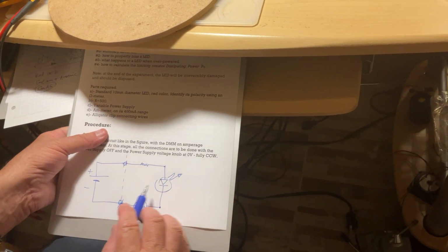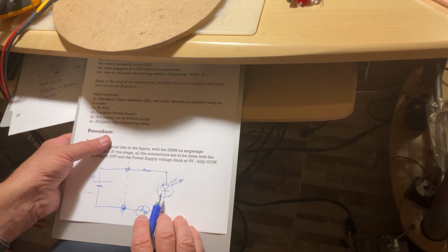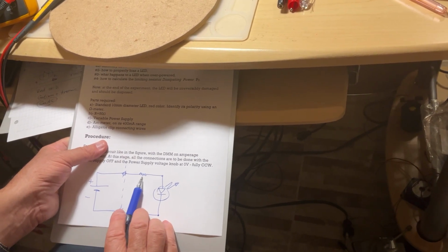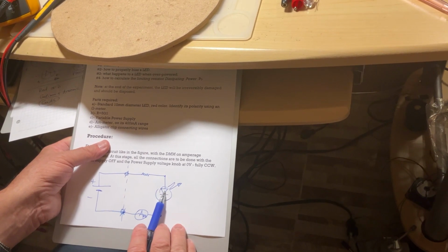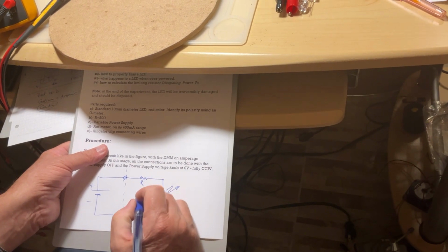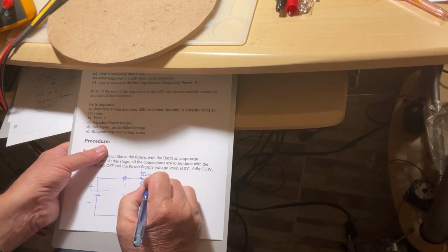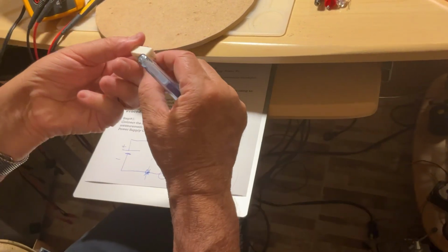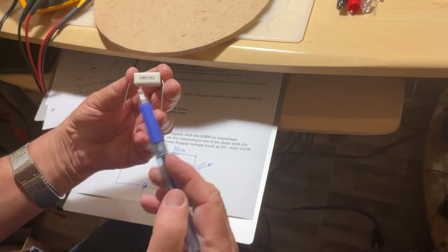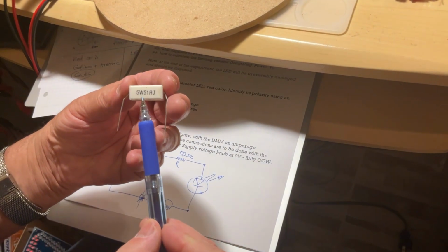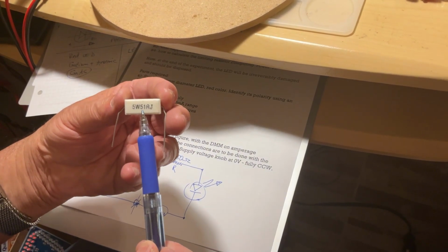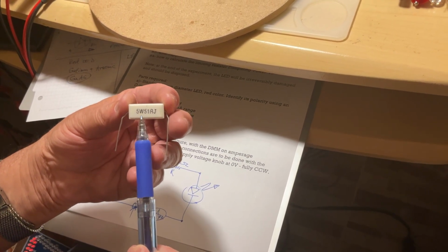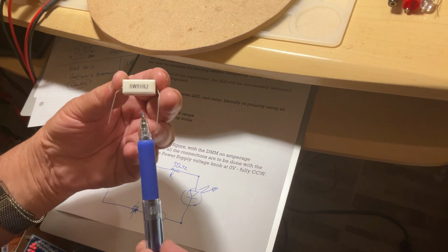As a general rule, for all the diodes, regardless if they are rectifiers or LEDs, they need a limiting resistor, because in the absence of that resistor, you burn the diode right away. Our limiting resistor R is going to be 50 ohms. So to make sure, because we're going to put the diode in very harsh conditions, this resistor here, which is 50 ohms approximately, is a 5-watt resistor, because I don't want the resistor to heat up too much.